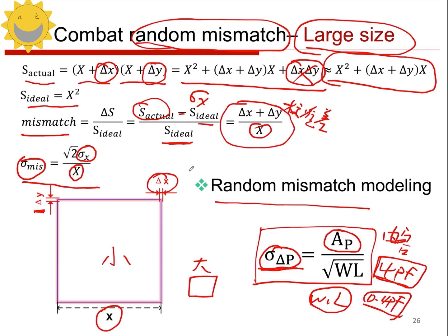So in analog circuits, we talk about the precision of precision circuits. It's directly related to power consumption. If your precision is high, then obviously your power consumption will also be high. The most direct reason is that if your precision is high, the size of your devices will be larger, and when you drive such large devices, your current will also need to increase. So it's clear that your power consumption will also increase. Using a larger size can reduce random mismatch.